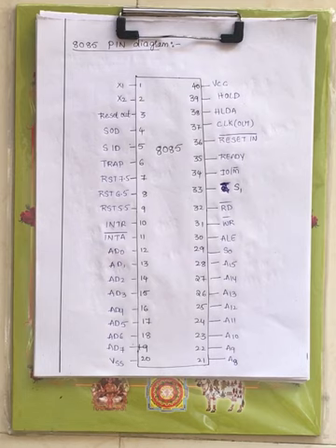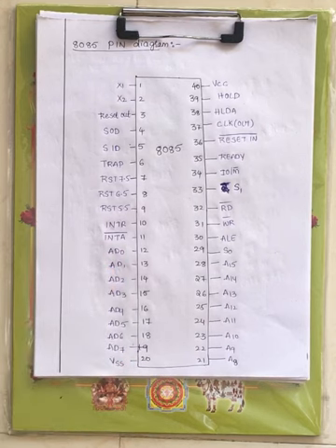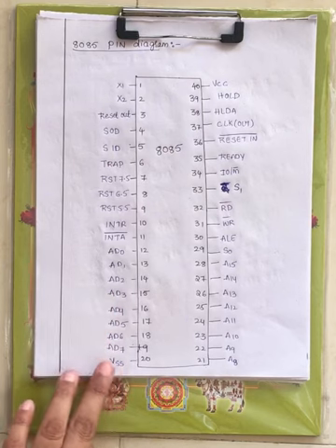Now if you see the data bus, how many data bits are available? D0 to D7. That means you can carry 8-bit data through the data bus. This point you have to remember. The address bus for your 8085 microprocessor is 16-bit, and the data bus is 8-bit. Since it is an 8-bit processor, it will perform 8-bit arithmetic and logical operations. Hence the data carried between the processor and the memory or the IO devices is of 8 bits, since D0 to D7.